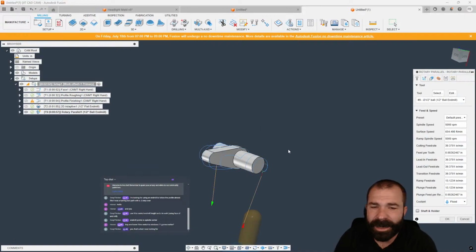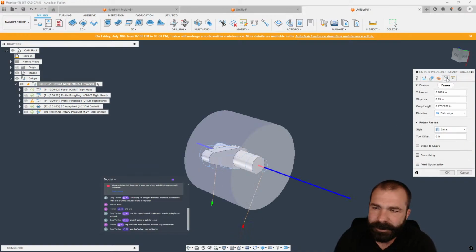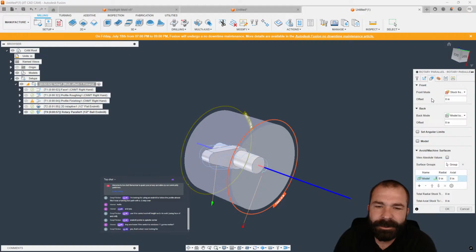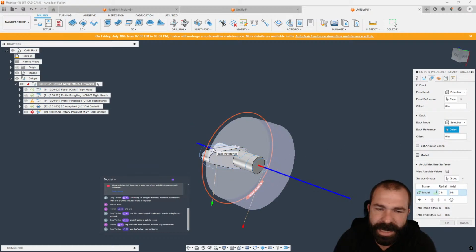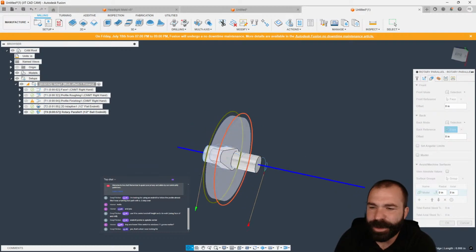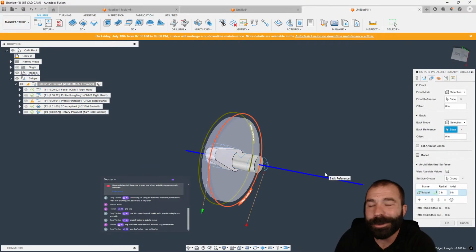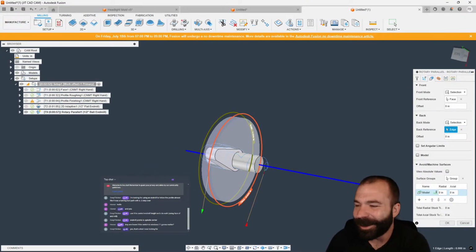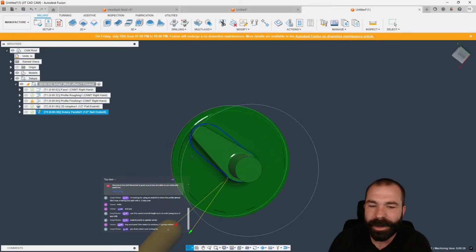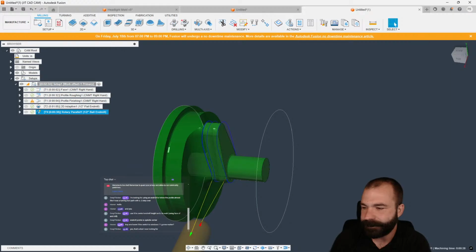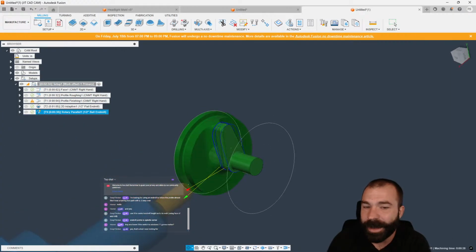So as you guys can see now, if I go back one more time, I can actually change things like my geometry. For example, I want to start from a selected location, and I only want to machine so far back to another selected location. Now, for those of you that may or may not know, when we ran into trouble a couple weeks ago working on one of Tim's parts, sometimes we have to offset and start in front of things of that nature to get our toolpath correctly. But as you can see now, I've narrowed down where that ball end mill is going to go around the part. So again, Deep Thinker, it looks like that's what you were looking for.